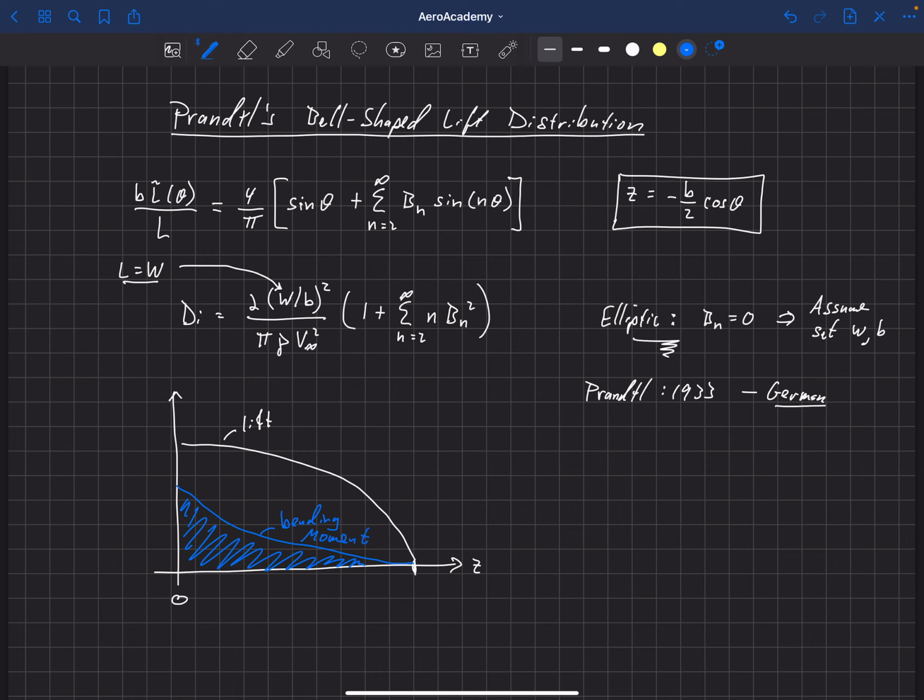Okay, so there's a relationship here. The bending moment, whatever it has to support there, translates to the size of spar that is needed. So this information gets used to size the spar. And then the size of the spar factors back into the weight of the aircraft up here, okay?